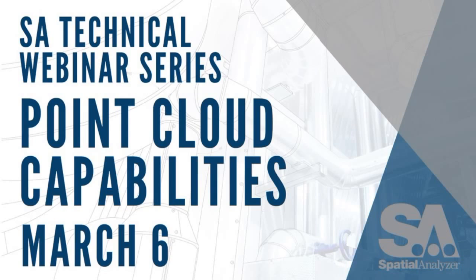and close. And let's say now we want to compare our cloud data to our nominal geometry. It's another thing that's very easy to do. We can go to Features, select our nominal from CAD. Let's go ahead and take this main bore. I'm going to call it main bore.